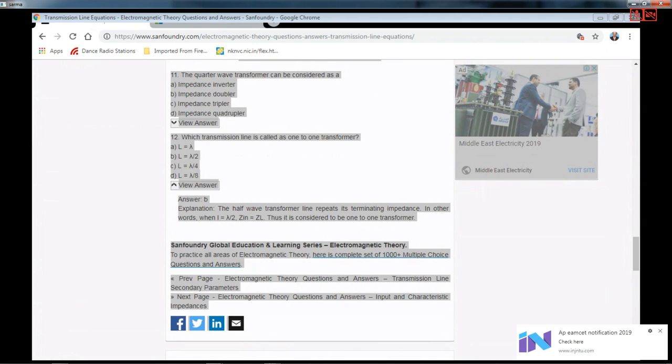That means how much part of the incident power is reflected, is not utilized by the load, is kept back on the transmission line, which is going to be troublesome for us. So how much is the troublesome component with reference to the input component we are going to take, and here we have a new parameter of interest: ZL minus Z naught by ZL plus Z naught, that is load impedance minus characteristic impedance of the line by load impedance plus characteristic impedance of the line.